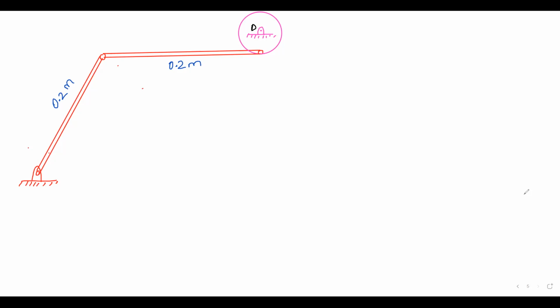1.5 is omega AB, right? No, it is alpha. Alpha, sorry. It's alpha AB. Oh, for sure. Okay. But omega BC and alpha BC you don't know. So what you will do is you will write VB equal to VA, write that equation and get hold of VB. Done. That will be an answer value.